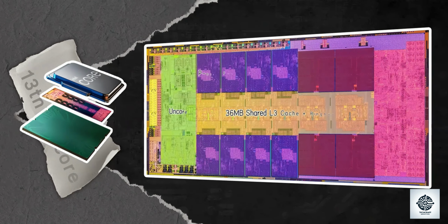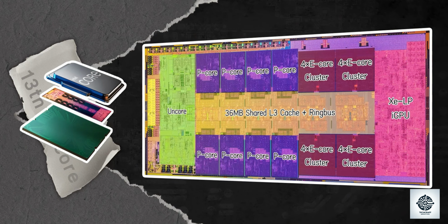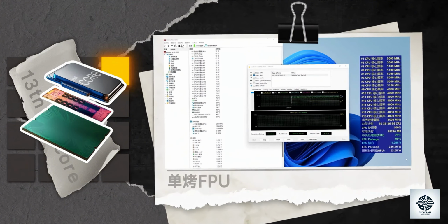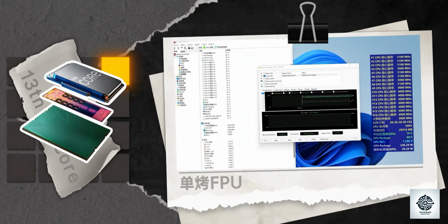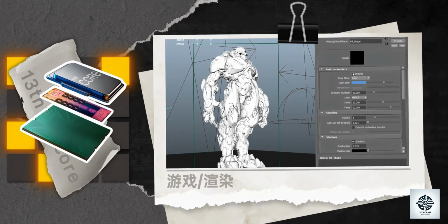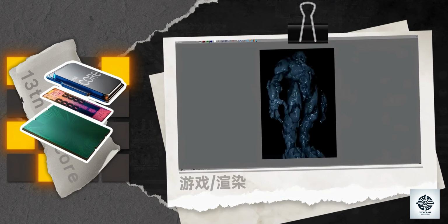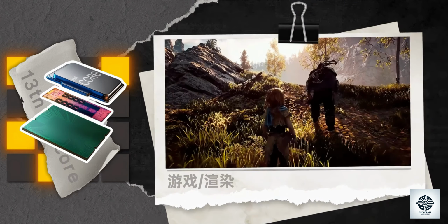Inside a CPU, there are many components such as the arithmetic logic unit, ALU, memory buses, and controllers. In stress tests like the FPU stress test, usually only components like the ALU and cache experience high load. However, when the CPU is in actual operation, all components can be activated simultaneously. This means that in a very short period, the CPU can reach power consumption levels far exceeding what occurs during tests, leading to higher than expected power figures.